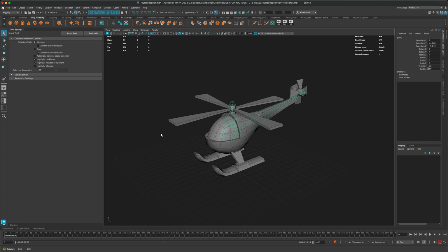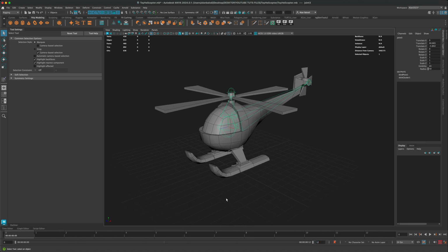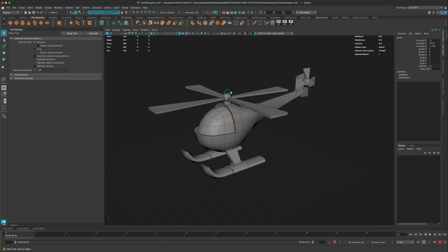And let's go ahead and maybe animate it as well. I'm gonna go down to my timeline down here and let's switch this to something small, maybe 12 frames. So it's currently 24 frames per second, which is fine. And my timeline is 12 frames, right? So what I'm gonna do is I'm gonna select this first joint. I'm gonna press S on my keyboard. And when I press S, you can see a keyframe has been set. There's a red line indicator. Now what I can do is I can drag it all the way down to 12.